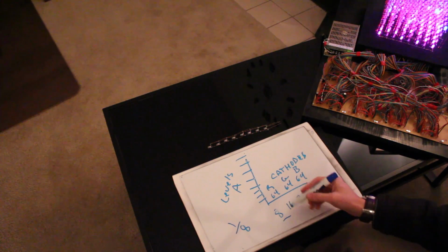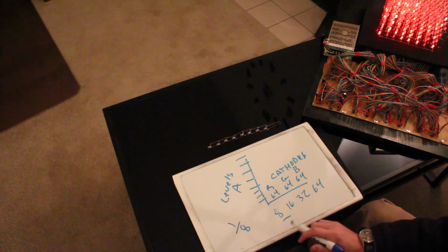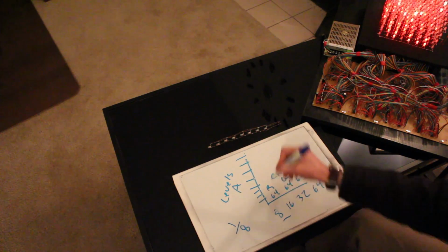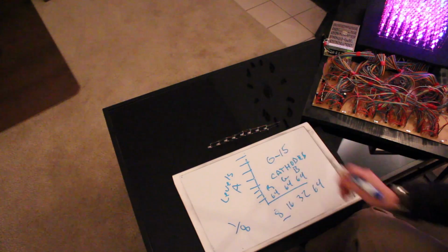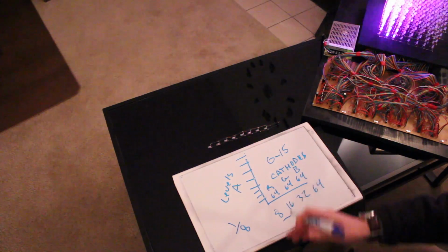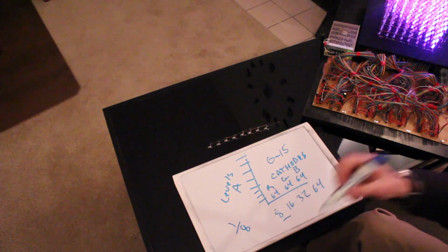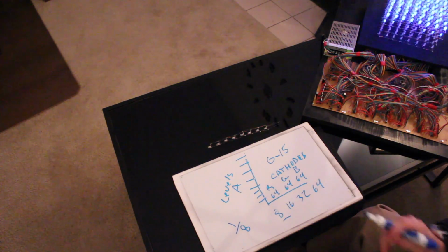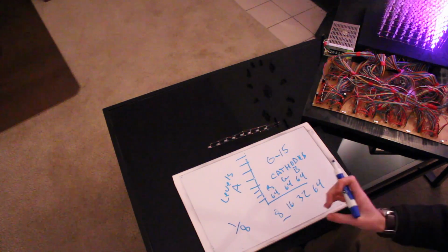Okay, so it's actually something like this. So I could write any value I wanted to it. Actually, the most I could write to it is 0 to 15 as a brightness. So just like I was telling you on the Arduino pin, you can do an analog write of 255. In my case, you can only write a value from 0 to 15.